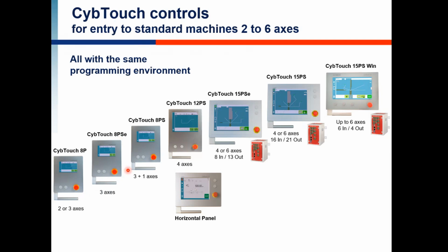Those Cybelec are by default numerical programming, which means you can enter one angle, 90 degrees, then enter the position of the back gauge, and add a few steps, change the bending parameters, the dwell time, the TDC, and so on. We have an option on them that is the 2D, where you can draw the profile on the screen. This is a tactile screen, so you can draw the profile with your fingers and select the bending order. This is, however, an option.